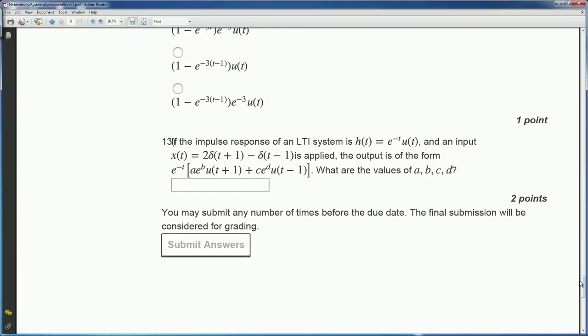And the 13th one is also a pretty standard LTI system question. You have the impulse response, you have the input. I mentioned the property of how to find the output. It's a convolution, and here you have these delta functions and unit steps showing up, and these kind of questions build up your comfort in dealing with delta functions in calculations. So how do you do convolution with delta functions? How do you do convolution with delta of t plus 1? Okay, there's a property of the delta function which was described in the lectures. You can go ahead and use that and solve the problem.